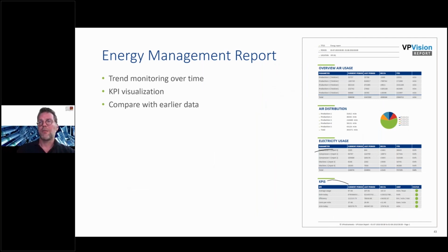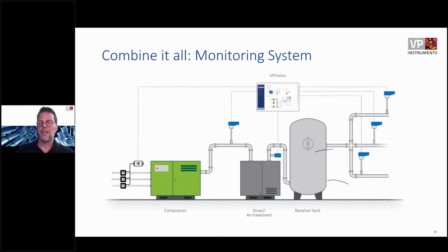Also, undersizing sometimes happens. When you use an undersized flow meter, then of course the flow will clip at some point. It cannot go higher. And in that case, of course, your number is not correct anymore.